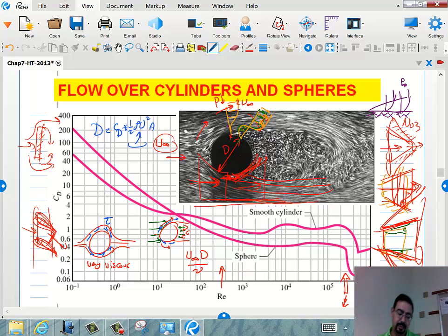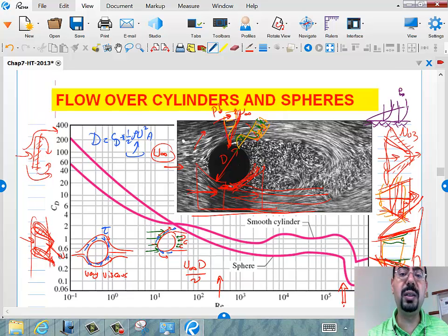Right? So you kind of understand now why the flow separates. Because the pressure in front of him is killing him. It's killing the boundary layer. Let's look at this boundary layer profile. The higher and higher pressure that it has to go through, once it has crossed this point and starts going downhill, will reduce the velocity near the wall.